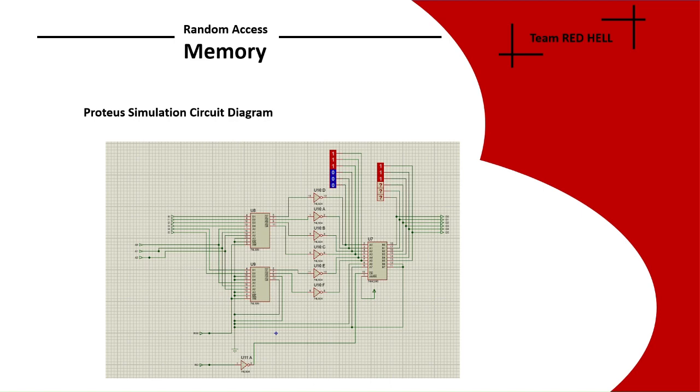The main downside of this IC is that the outputs are active low, so we had to use 6 NOT gates. Here we can see the outputs are going to the bus. We further added one more IC, which we'll be discussing soon.